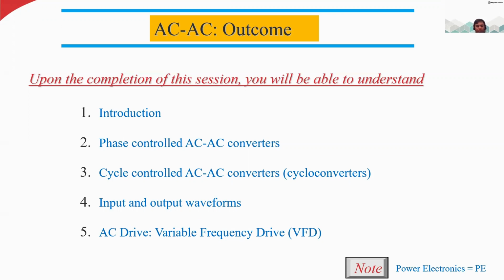So if you want to control the speed of the AC motors, then you have to control the frequency. So how can you control the frequency? That is the device called VFD. So we have to use the VFD to control the frequency and the speed of the induction motor, let's say AC induction motor.